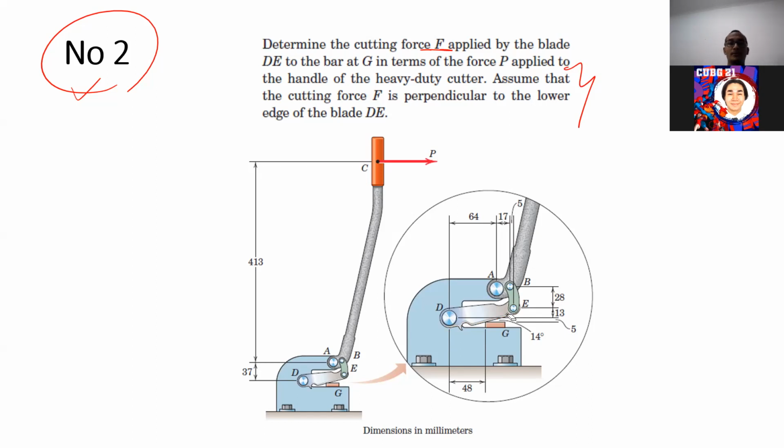As I told you before, the shape of a 2 force member can be anything. As long as you have 1 member, whatever the shape is, and it has pin joints at both ends, and the load comes only from the pin joints, and there is no friction there, no moment at the ends as well, it will be a two force member.